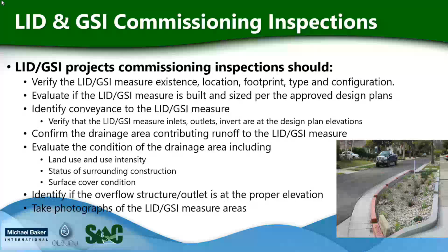the design plan elevations. Confirm the drainage area contributing runoff to the LID and GSI measure, and evaluate the condition of the drainage area, including the land use and intensity, the status of surrounding construction, and surface condition. We want to make sure that the drainage area is fully stabilized. Identify if the overflow structure is at the proper elevation, and of course take photographs of the LID and GSI measure areas.